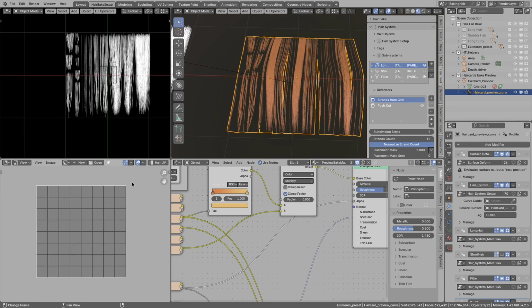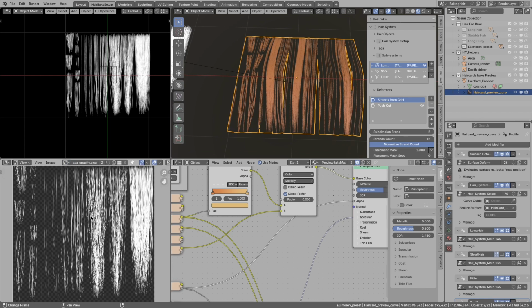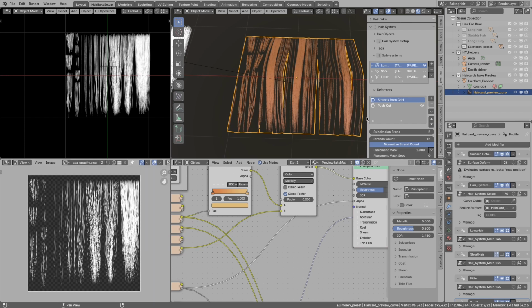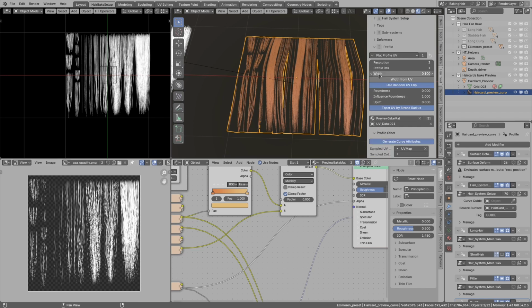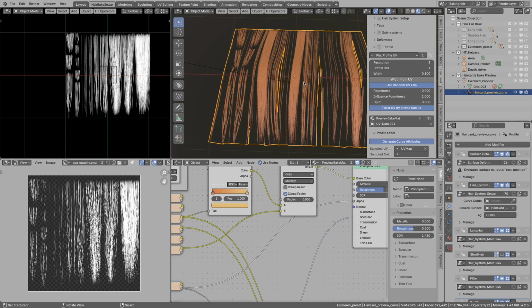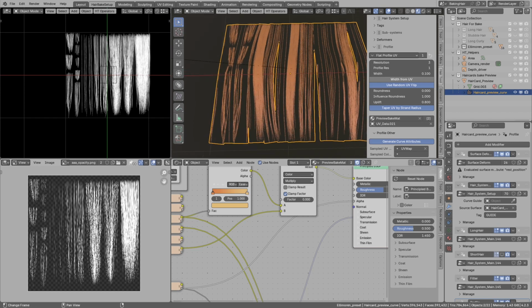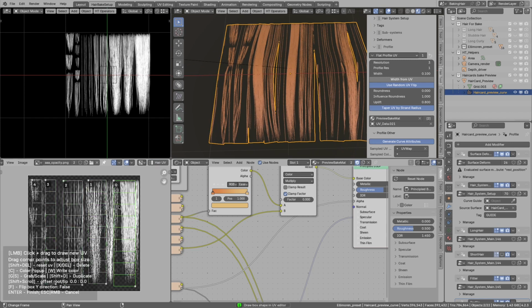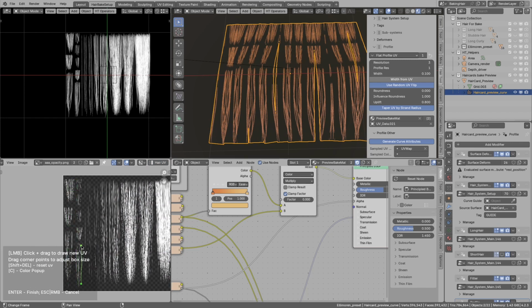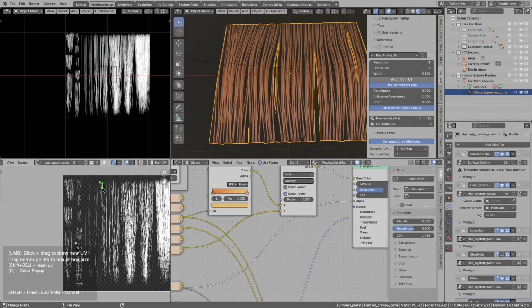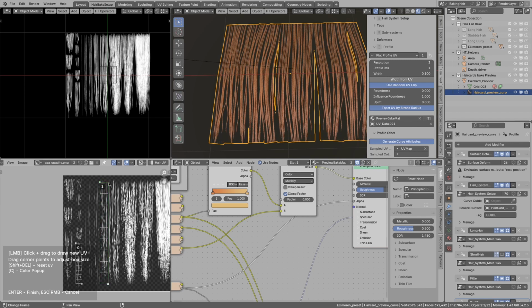Let's load the texture we baked, the opacity, and just as a reminder, the UVs are stored in the profile in this object. So let's edit the UV layout. In the top header bar for the image, select the Hair UV button. I will press X and remove a bunch of those old UV boxes. Resize those ones. I will just make this quick, but I want to use all the regions.